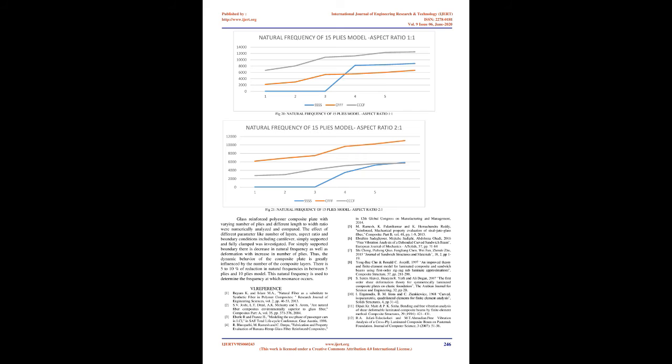2. Methodology. 3. Material selection. Mechanical properties. Poisson ratio. The characteristics of a fiberglass composite plate can be determined completely by four material constants, E1, E2, G12, and ν12, where the suffixes 1 and 2 indicate principal material directions. For material characterization of composites, laminates having different layers were manufactured to evaluate the material constants. The dimensions of the specimen were taken as specified in ASTM D638, represented in Table 3.1 below. Properties of glass reinforced polyester. The mechanical properties of the polyester composite plate are given below.